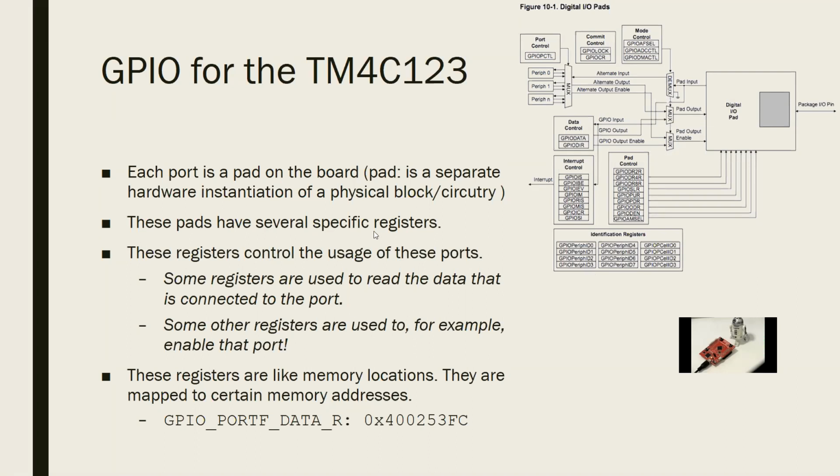Okay, and they've got specific registers. Some registers are used to read data. Some registers are to enable that port. Some of them to designate the direction of that port, input or output pins. And in the end, the most important register was the data register, because we used to write or ignite the LEDs to make the LEDs bright. Because when we write to this register, the data register, if we make the necessary configuration, we were able to change the output pins which were connected to the LEDs and thus change the colors of the LEDs. Okay, pretty much a summary, I guess.